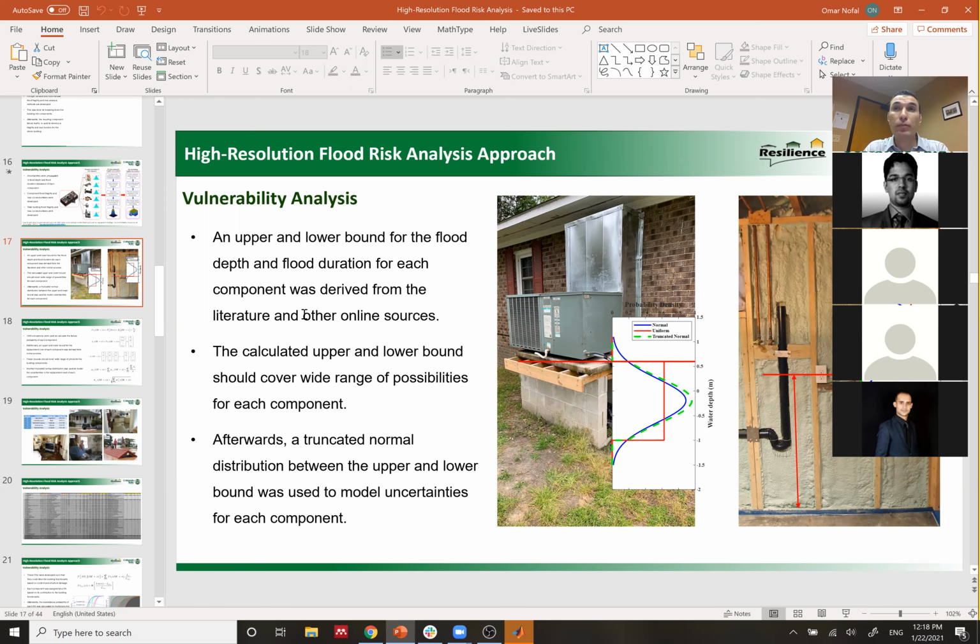The main thing that makes flood a unique hazard is that it has more content damage than structural damage for riverine flooding or static flooding, which is different from flooding from surge and wave. So we care more about content, because the structure will be safe, but the content will be lost. And the content is also essential for the occupability of the building.